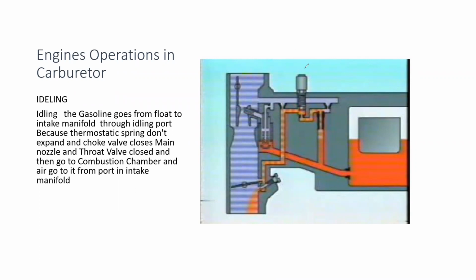Next, before I go ahead, I need to point out something. There are these components that you won't be seeing in the other image. The reason being, this is actually a solenoid valve. This is available in all of the carburetors. The reason for this is, without this solenoid valve, the fuel will always be open. If you can push the vehicle hard enough, the engine will automatically start with or without the key, right? To avoid that, assuming the ignition system works, this is there as a secondary fail-safe system.